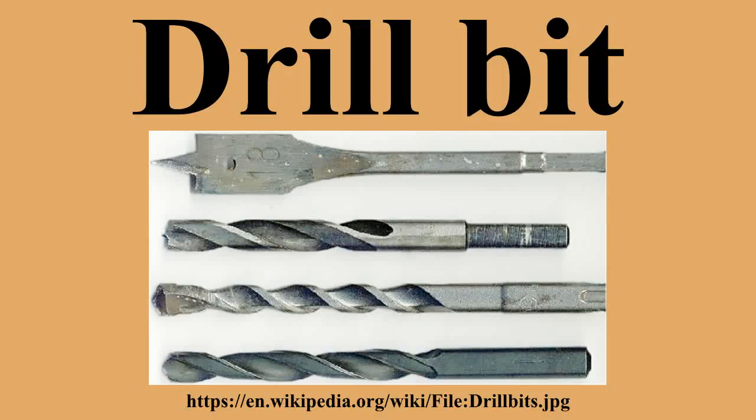A more aggressive angle, such as 90 degrees, is suited for very soft plastics and other materials. It would wear rapidly in hard materials. Such a bit is generally self-starting and can cut very quickly. A shallower angle, such as 150 degrees, is suited for drilling steels and other tougher materials. This style of bit requires a starter hole, but does not bind or suffer premature wear so long as a suitable feed rate is used.